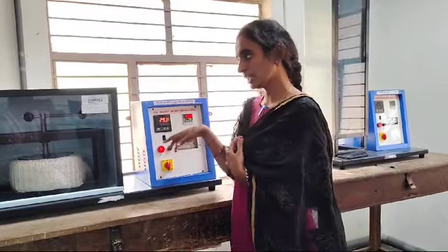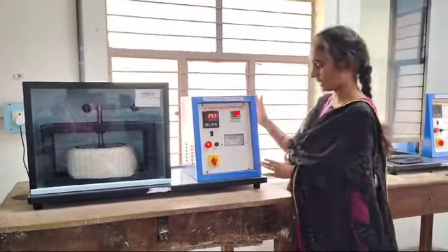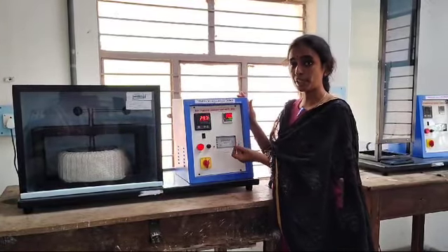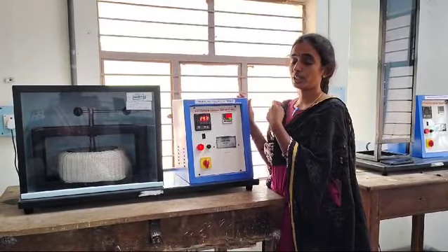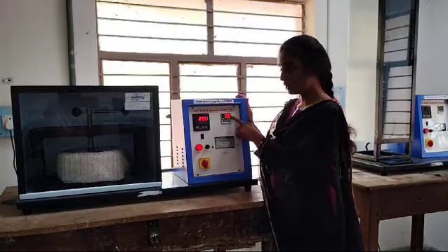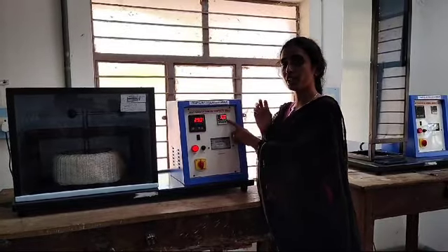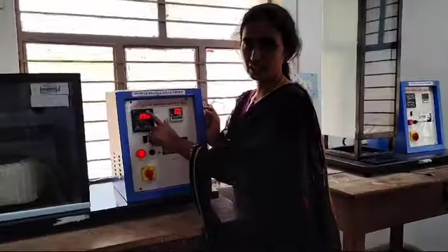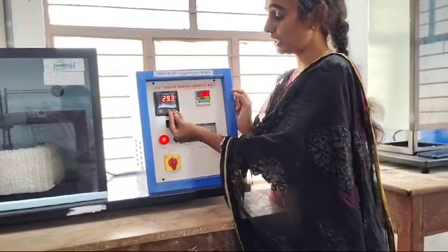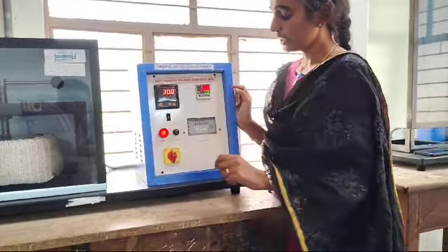Coming to the equipment description, this is the composite wall made up of three different materials: cast iron, bakelite and wood. This is called the control panel, where we can control all the experimental procedures and get the temperatures of the equipment. This is the heater, this is the process variable, which is the temperature at a particular time, and this is the set value, where we set the value for the system. This is the digital temperature controller, where we can display the temperatures at different points of the system. This is the channel changer.